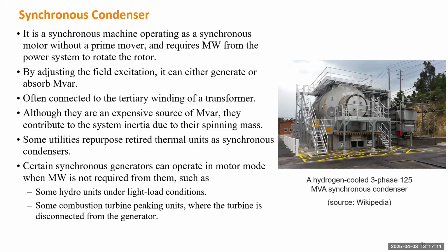Okay. And when you have more and more renewables in the system, you need to have spinning reserve. Remember the duck chart we talked about. If the solar needs to drop quickly within 1 or 2 hours, you need some generation to pick up. It's better they are just spinning there, and they can easily increase their output by the load frequency control. Such units, if they're not providing any power but are running there, can be utilized as synchronous condensers.